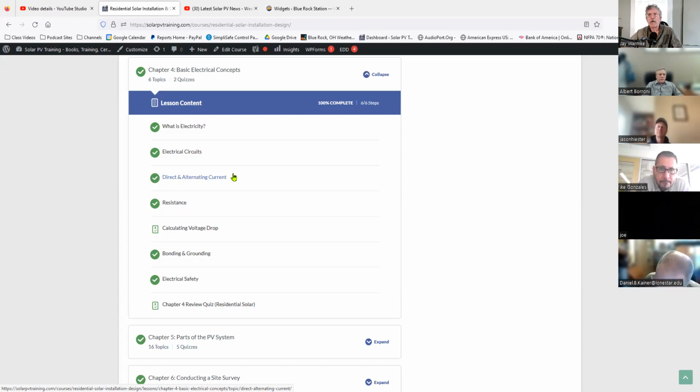You know, so to increase the robustness or the size of my system so that I can get more power over time. So we do a series and parallel kind of design for our battery bank systems and for our arrays. Those are fairly typical that we do both. There's no easy way to remember it except to just remember it. I always think of there's an A in parallel, so that's for amps. There's no A in series. That's a little mnemonic you can use.